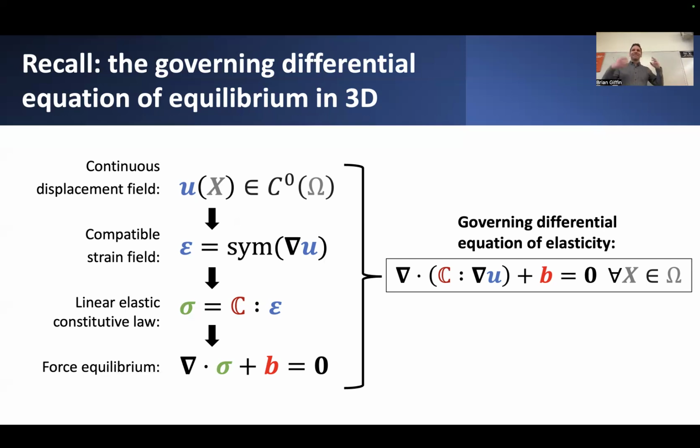But in any case, this rank 4 tensor provided us a way of relating all of those 9, technically 6 independent components of strain to the resulting 9, technically 6 components of stress. Remembering that both the stress and strain tensors are themselves symmetric tensors. So if we wanted to define everything in terms of the 9 components of strain to the 9 components of stress, really there's only 6 independent components of each of those two things.